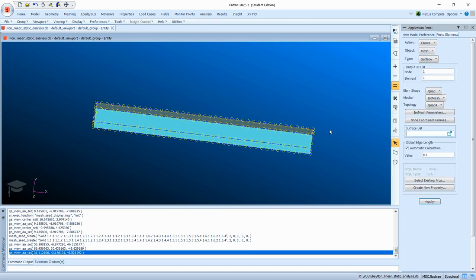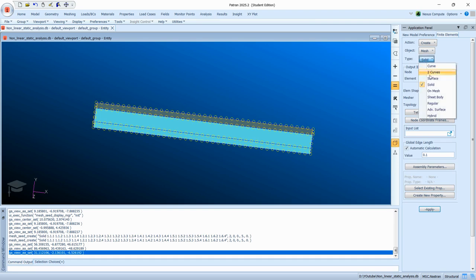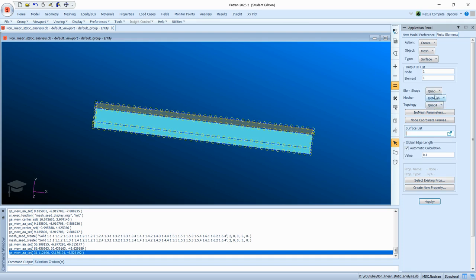And if you go to mesh, as I have a solid element, I'm not going to use the surface option. This is not very adaptable. You use the quad when you have two dimensions, plate, all that kind of stuff, and tria. But first of all, here, not surface. You go solid, and then you have the tet. That's what you use. If you put surface, you can see here it changes, either quad or tria. So you go solid, and now it will propose what you can use on solid: hex, wedge, and tet. Then you pick the tet mesh, Tet10. I think this is fine for me.